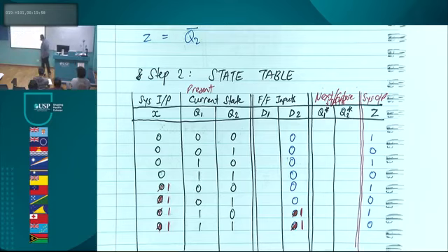So we've done the Z. How did I do Z? For those of you who have finished your D2, how did I do Z? Basically, Z equals Q2 bar. I hope my Q2 bar is correct. Q2 bar is a flip of Q2. So you just flip the bit. All this, you flip it and put it there.